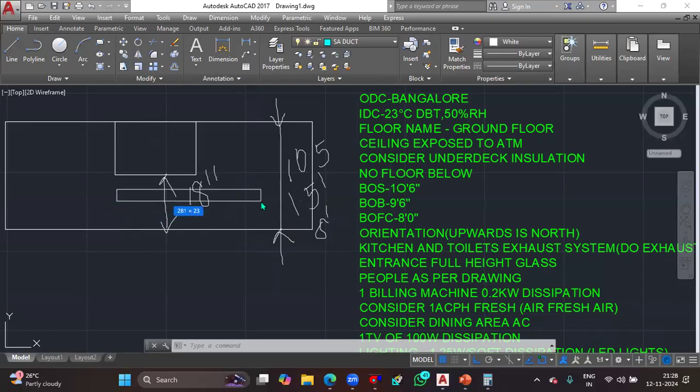That's why we can conveniently give some more extra clearance. That means now the height of the duct should look like this by providing a 2-inch offset on both ends. So here 2 inches offset and here also a 2-inch offset. The total should now be 14 inches. Still you can reduce the height to 12 inches, 10 inches. But tomorrow I will explain till where you need to reduce the main duct value. Normally you can constrain up to 12 inches. All right, so this is how you may consider your duct height for your projects.